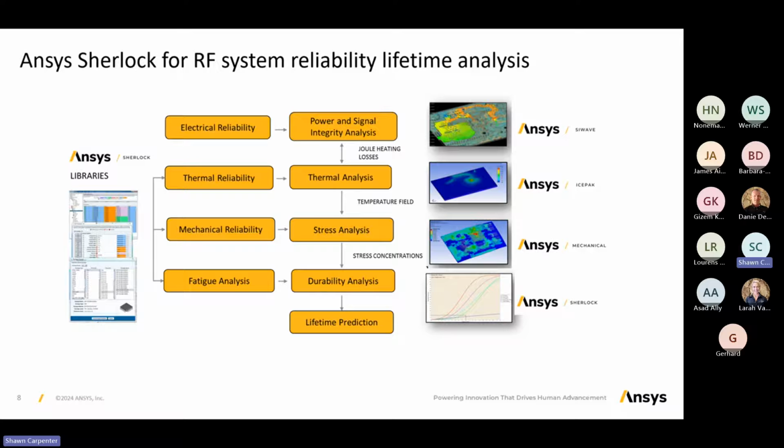Now, we also have, as I mentioned, a complete workflow for RF system reliability lifetime analysis to predict, for example, the mean time to failure or the 90% lifetime or whatever lifetime window you need for a complete populated board. And that's under our Sherlock products. I'm not going to talk any more about that, but just know that that is a complete multi-physics coupled analysis flow with component level information, so that we take into account the reliability of every component that's populated on your board as you then apply a physics simulation to the board itself under duress of power up and all the things that we do, heating and so forth.